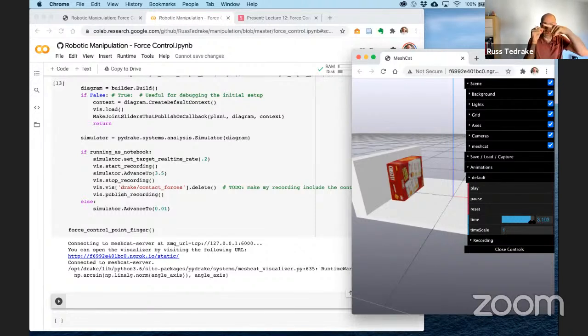And then once my desired theta moves beyond the threshold, which would compensate for gravity, then the PD control term alone would achieve the trivial greater than mg constraint. We should look at it actually. We have everything we need to see if that constraint is active. Because it's an error-driven controller, when the theta desired is at theta at the beginning, that's not going to be doing enough to resist the forces, so that constraint is probably active, and then as it moves forward, it would not be.